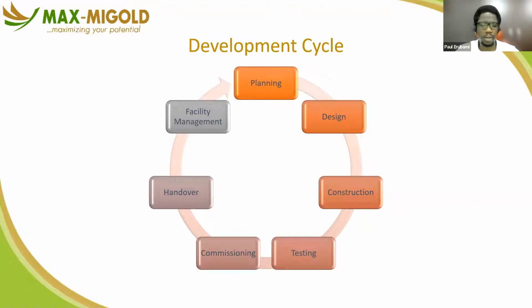All of those data: how much smoke came out, how much noise was within the range, what about the vibration, was it within the range of normal operations. You take those numbers down, and then you know that the generator is working normally. It meets the load requirements, and it does not shut down while meeting those load requirements. You can now certify that the generator is commissioned. Because commissioning may not necessarily be possible 100% of the time, because you may not have the load requirement, take a stairwell, for example. The stairwell was designed to effectively evacuate 100 people from every floor.